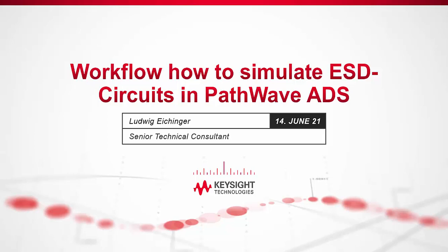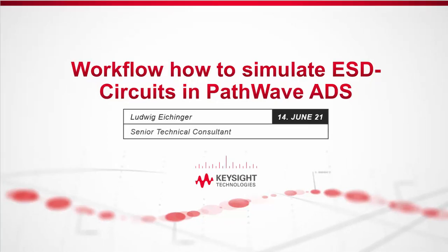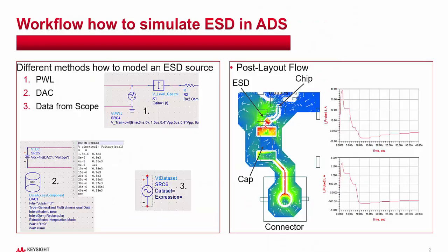In this video, I will illustrate the workflow for how to simulate electrostatic discharge circuits in PathWave Advanced Design System (ADS) from Keysight to protect the electronics on a PCB against damage. At each input and output interface, or say at each connector, the electronics should be protected with an electrostatic discharge circuit. In the first part of this video, I will show different methods for how to model an ESD source or pulse.